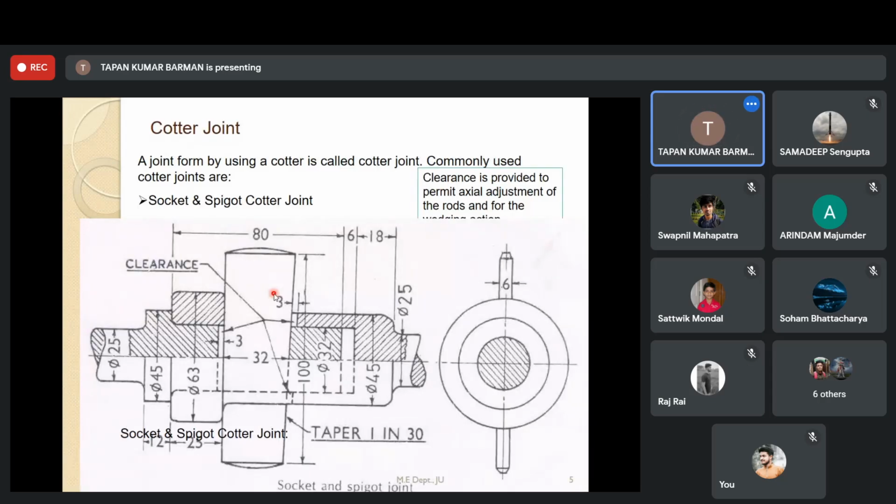Here also you may identify two things. In these two components, the hatch lines are there up to the center line. This center line is basically the line of symmetry, so above this and below this there should be the same features. Now you see we have put the section lines above the center line. Is it full section or half section? Can you say?